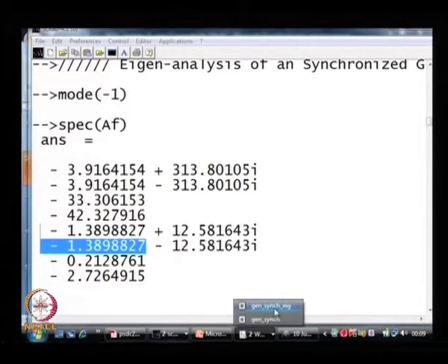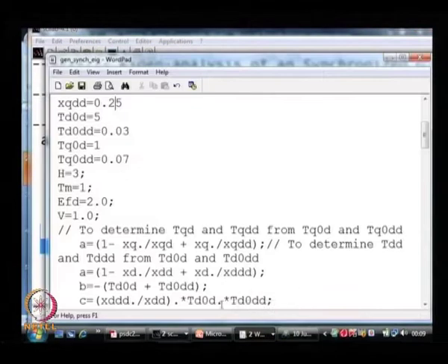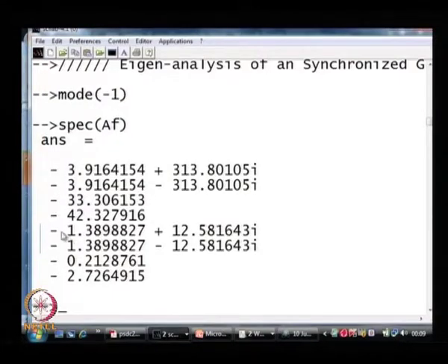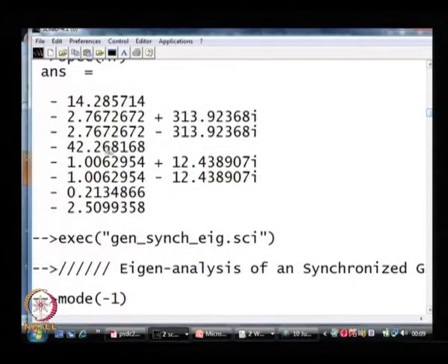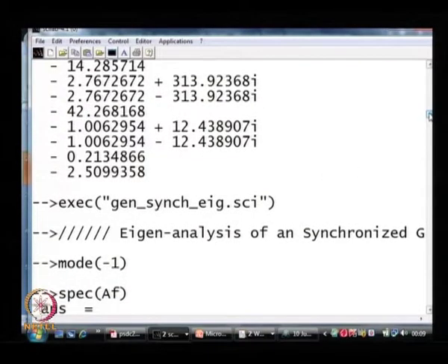In fact, of course, we need to just check out the operating point which we are talking of. Yeah. So, what we see here is, of course, that if I take the 2.2 model, the real part of the eigenvalue is 1.4 roughly, whereas the eigenvalue here is 1. So, you see that with the 2.1 model, the damping of the swing mode is slightly lower. Okay.